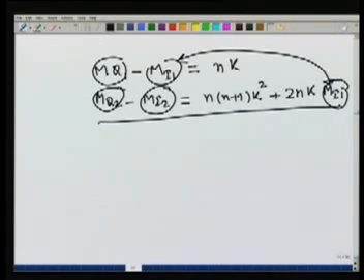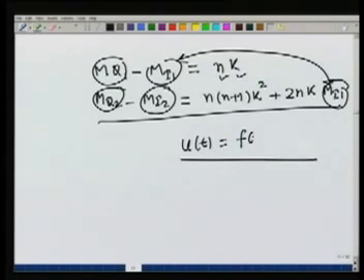So if we have these 4 values known from an ERH and corresponding DRH, we can estimate the values of n and k, and once we have n and k, then we know that the IUH ordinate is given by the gamma function, exponential, and all these. So these two, n and k, are the parameters which will depend on the catchment and may be obtained from an available ERH and DRH value. So the IUH, which we have discussed just now, takes care of any non-uniformity in the rainfall where we cannot approximate it by constant intensity over certain duration.